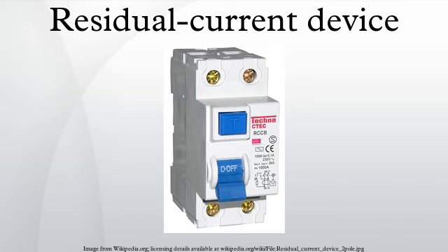Purpose and operation. RCDs are designed to disconnect the circuit if there is a leakage current. By detecting small leakage currents and disconnecting quickly enough, they may prevent electrocution. They are an essential part of the automatic disconnection of supply, that is, to switch off when a fault develops, rather than rely on human intervention. This is one of the essential tenets of modern electrical practice.